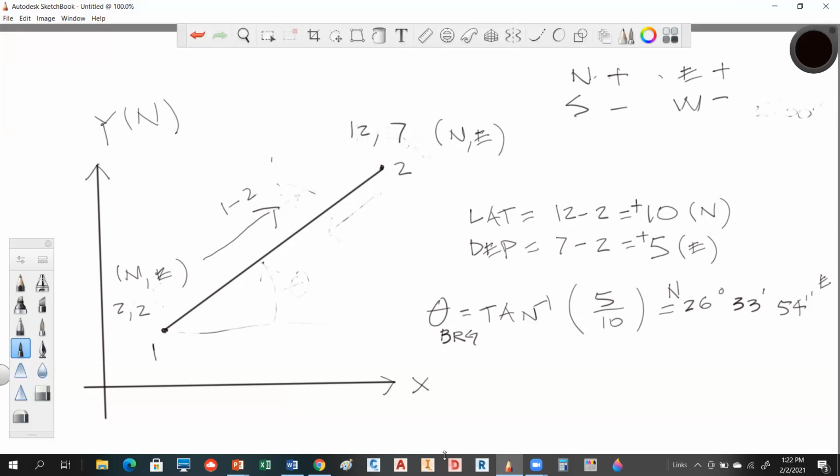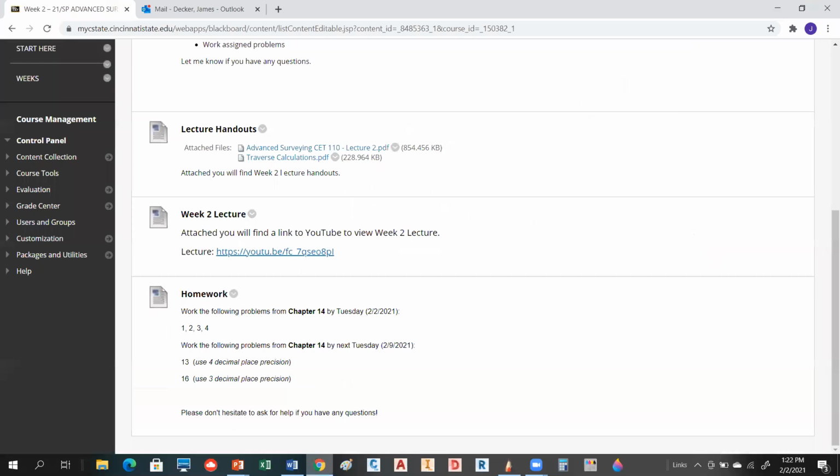So this is what we call this process right here, doing this and this. This is an inverse, inversing an angle. Okay, so we're inversing right here. Subtracting coordinates is inversing, and then what you're doing is calculating a direction at that point. So let's go over and look at distance.